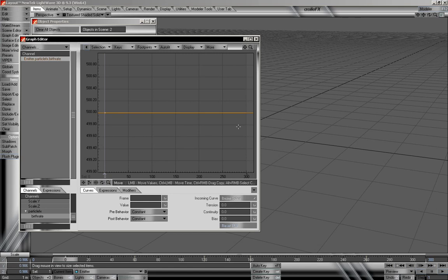But what I want to do is towards the end of the animation, or even in the middle, just set a couple of different keys. So if we go down to the lower left, we can see our key. And we could just select that, and now left mouse click onto our timeline to add some different keys. And now we can go up and down with this just to generate some different birth rates. Now keep in mind, what we're seeing right now is just 500.8 to 499.